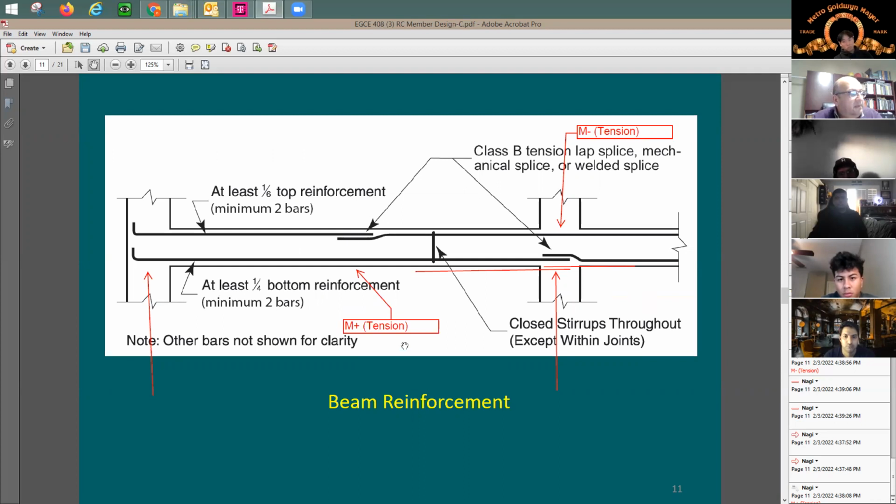Yeah, look at this. Tension the bottom, compression the top. This is where I put the splice in this section here. Tension the top, compression the bottom. I put the splice in compression, and this makes sense. Because when you have tension the rebar, it's going to be kind of tough to transfer the force from one rebar to the other rebar in tension without causing some cracking. So in a case like this, you'd like to put the splice to be in compression as much as you can.